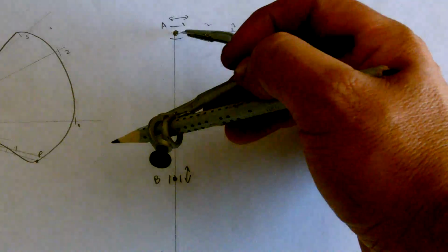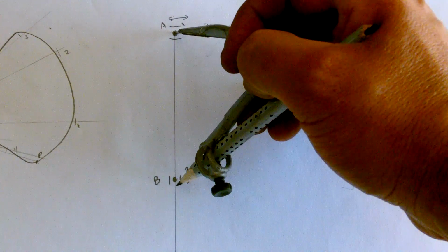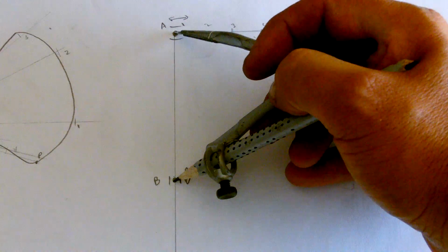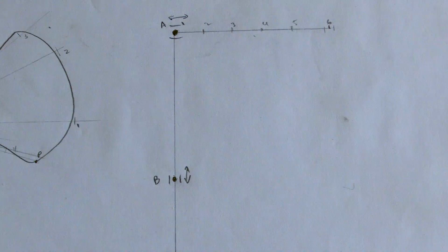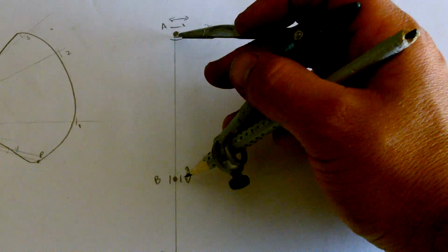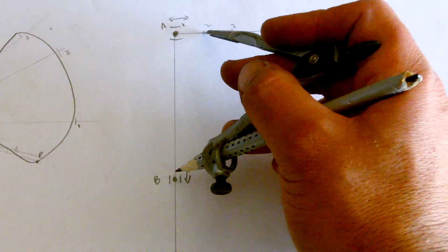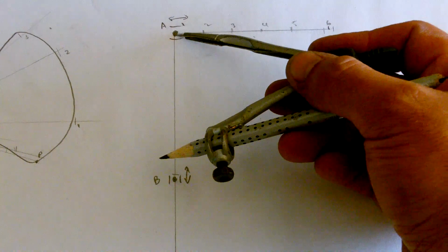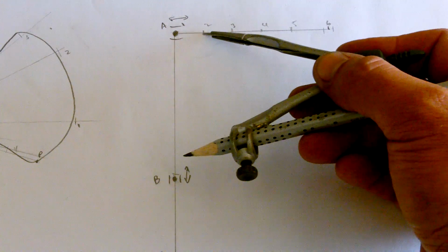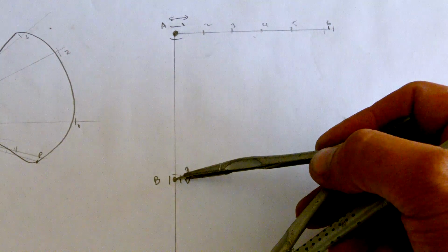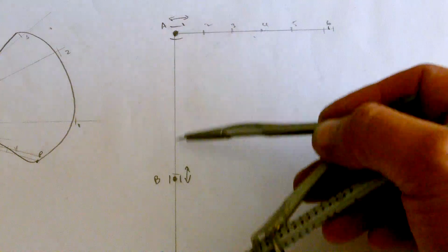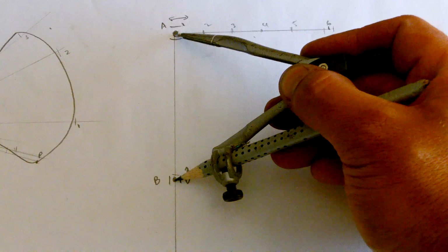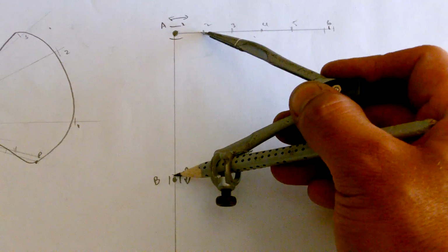So when A moves this distance to position 2, what happens to B? I'm going to take the distance from AB, because these are the 2 points that are determining my movement. They're fixed. A goes here, B goes slightly upwards. Many make a mistake: if A moves this division here, they take B up the same division, same distance. Well, that will reduce the distance from A to B. What you want is always keeping that distance. So when A goes here, B goes there.